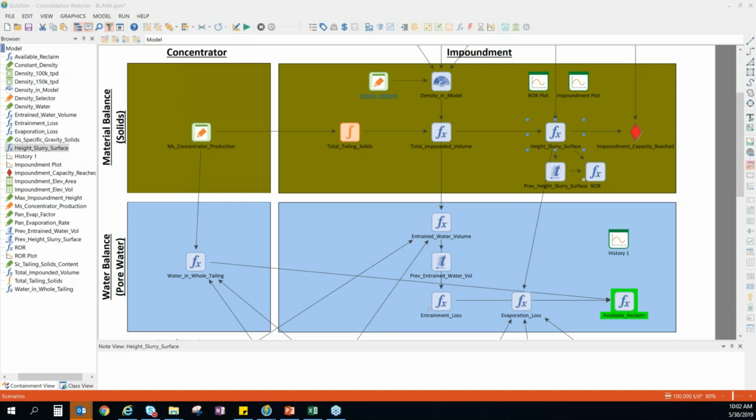This calculation method is still representative, but the tricky thing is, if your assumed density goes down, really that relates to kind of the opposite of consolidation, right? That relates to an expansion of the soil. So realistically, that's probably not happening, but the level of accuracy of surveys and things like that used to estimate the volume of tailing in the impoundment might be producing a small local effect like that.